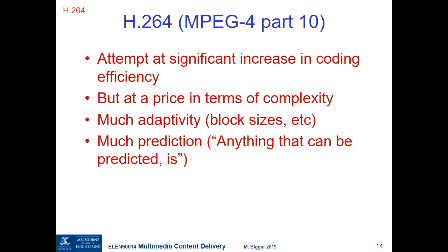Do we display the two pictures one by one or at the same time? In the analog world, we would display them at different times as well, and that actually helped. But these days, with LCD displays, we have pixels that are on all the time. We're just updating what they are. So if we show one field and then another field, we see all these little jagged edges. So that's the reason that we have some interlacing in the first place.